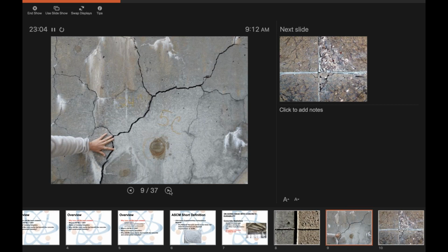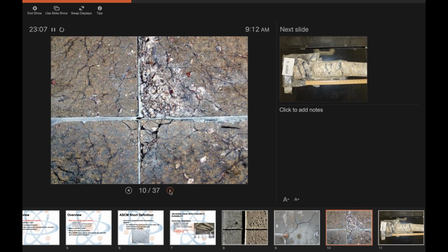Next slide, please. It's not even limited to our dams or our residential work. This is one of the airports out here in Colorado. Now, granted, this is ASR plus decracking plus mag chloride attack, but the harsh reality is we're beating up our concrete more. We've got more traffic, more transportation loads, higher alkali cements, and more reactive aggregates, and we want more out of our concrete. We want 28-day strengths in 24 hours. It should come as no surprise that if we burn the candle at both ends, we're going to start seeing things like this.